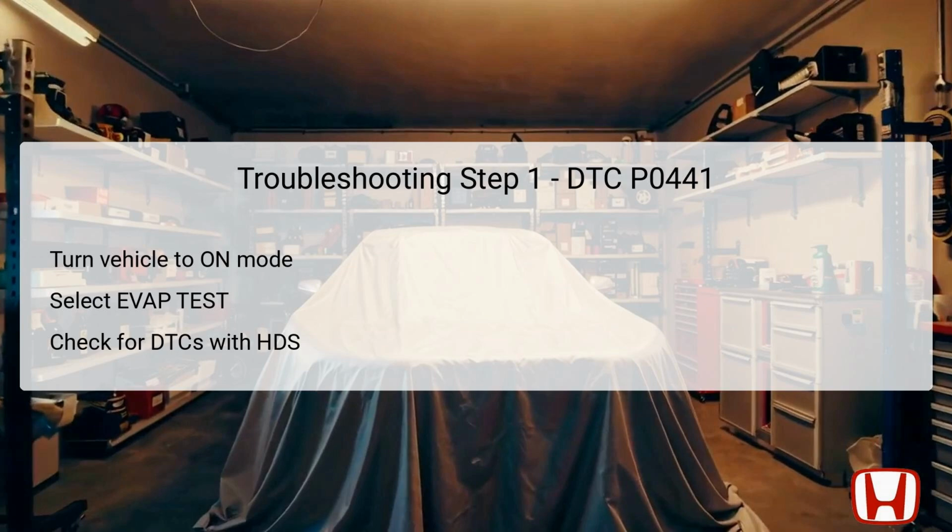After selecting the function, you need to perform a check for both pending and confirmed DTCs. This is crucial as it helps in identifying not only the current error code, but also any additional issues within the system that may have been detected by the ECU. Evaluating both types of DTCs will give a clearer picture of the vehicle's health and can guide subsequent troubleshooting steps. When conducting this test, ensure that you follow the manufacturer's guidelines to avoid any disruptions in the process.